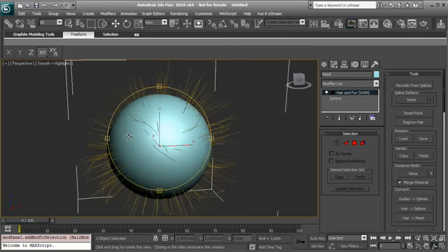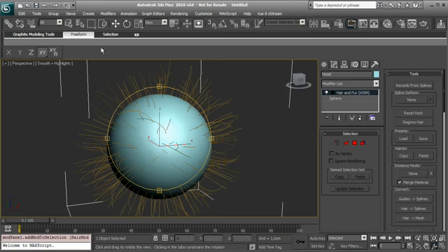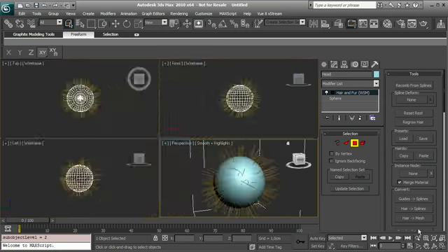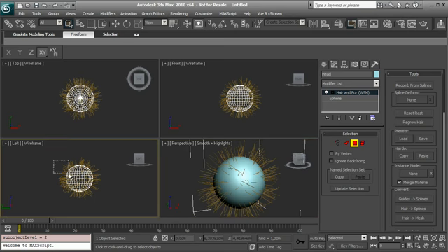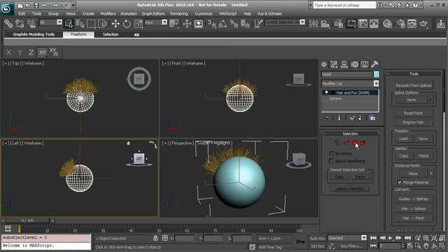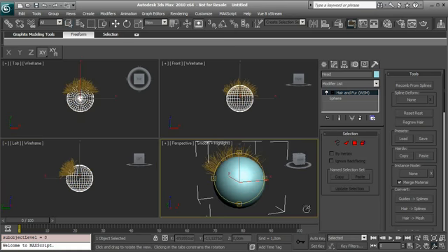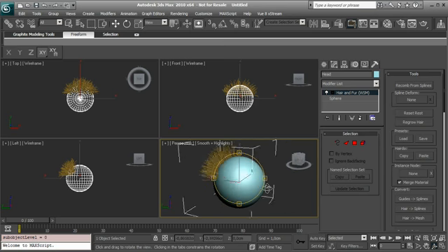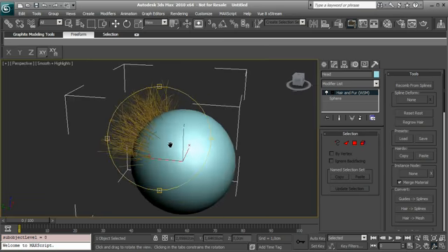If I'd like to have the fur or the hair just on an area of the mesh, I can go inside the polygon selection, and go, for example, to the left viewport. Let's select this area, let's close it, and you see that actually I have my hair just there. So for the moment we can use this area, it's not a problem.